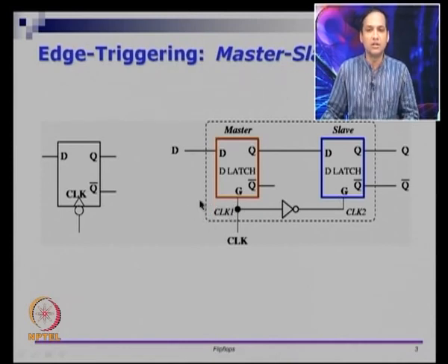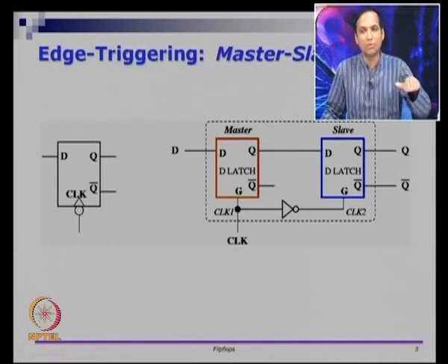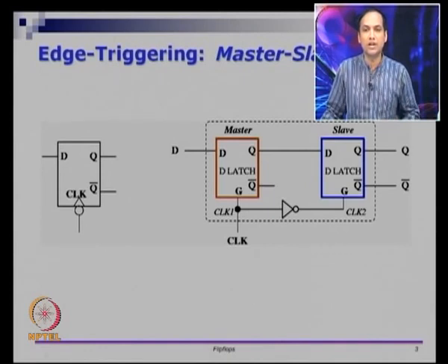Specifically, this circuit becomes what is called an edge triggered circuit. So, this circuit is not level triggered anymore. It is not that at a particular level of the clock D gets copied to Q. Once you connect it like this, with respect to this CLK, this D cannot be asynchronously copied to Q, which means the change in D can reflect as change in Q only at very specific time intervals, not any time that D desires to. There is also this bubble here, we will come to that in a little while.